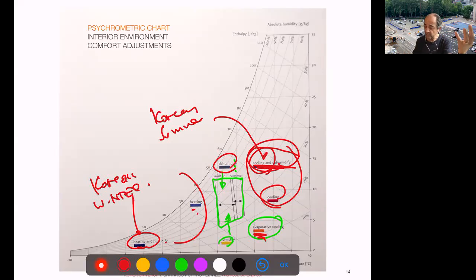And it would not be very wise because in Korea, in summer, the humidity is almost saturated. So that evaporation will not work, will not make things better. This is why we need just to take humidity out. Whereas in very dry climates, that works very well. And that is why that system was very successful in Spain, because as we said, in Spain we have areas with, at least temporarily, that kind of desert climate.